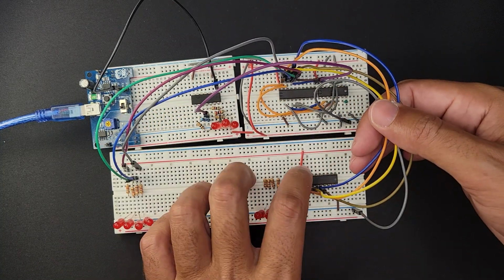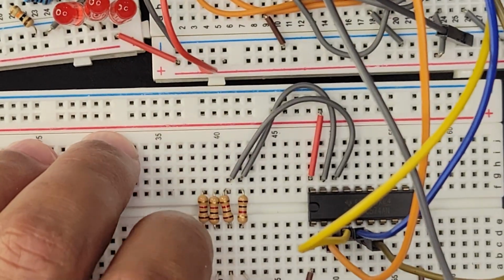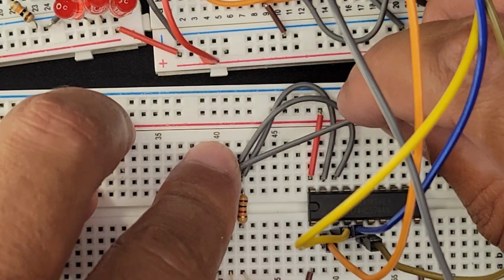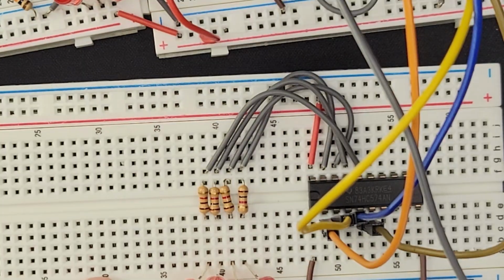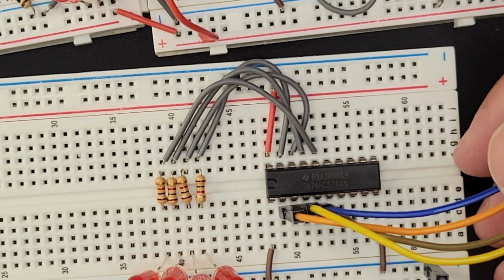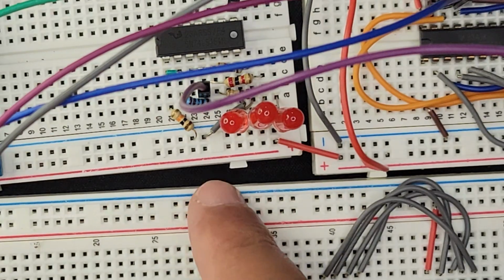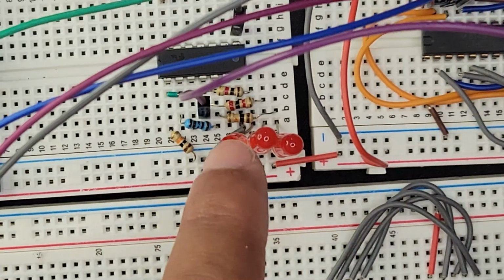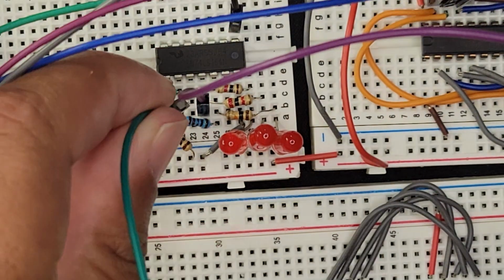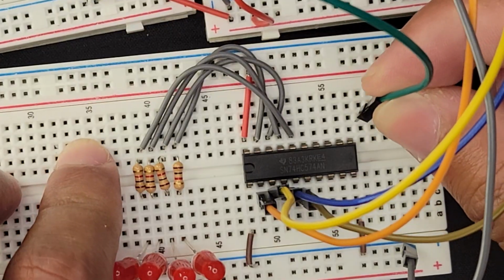Now we need the output into our LEDs. And I'm trying to line up the bits to be least significant bit on the right. So that's why the leftmost is going to the rightmost. And now all we need to do is pretty much connect the clock, I think, which is at top right. Right there is a clock. So that needs to come from the CPU state machine, the fetch instruction, right to the left of this purple wire. So I'm going to plug him in there. So when fetch is hot, we will hopefully synchronize.